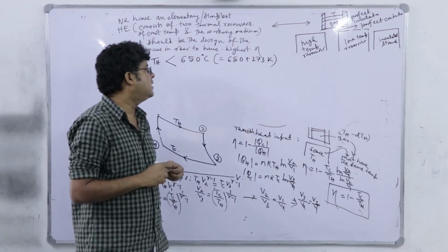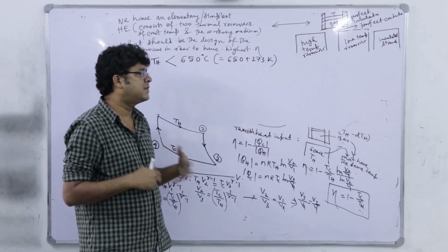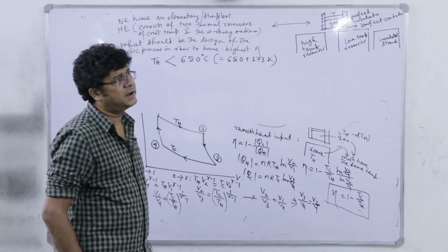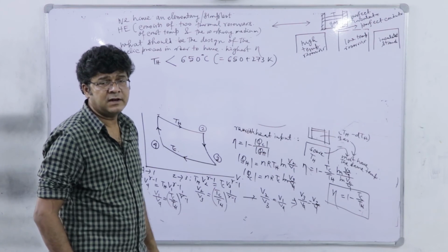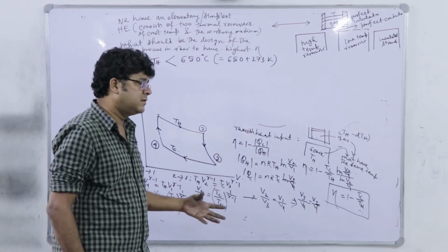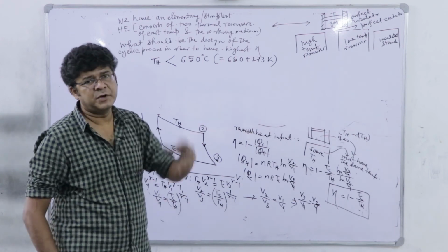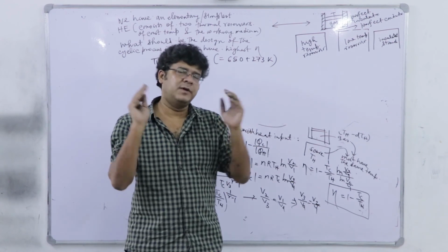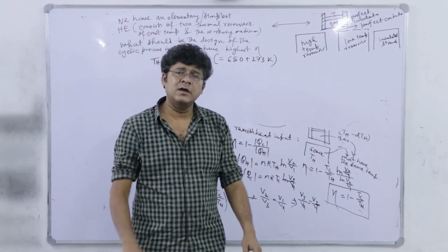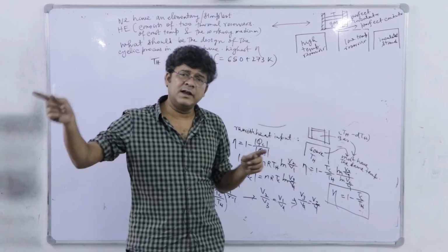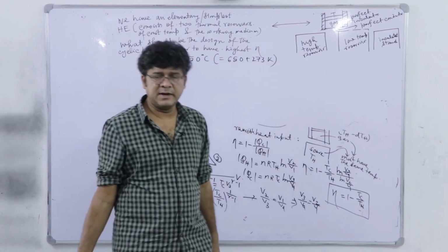Because in the boiler, which is the step where we deliver heat from the fossil fuels, it converts the subcooled water to superheated steam. Though it is not exactly isothermal, if I think of an isothermal analog in this theoretical paradigm, it may be saturated water which we are converting to saturated steam. So we can implement the Carnot cycle.